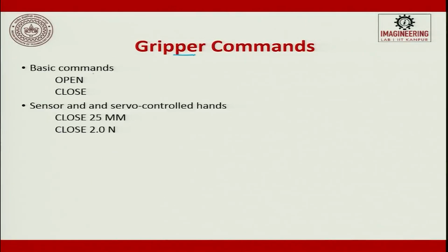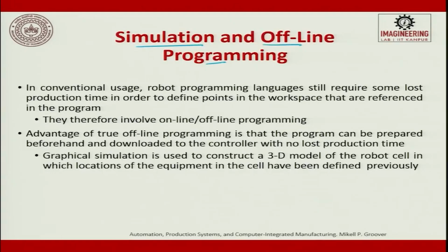The gripper commands can be basic open, close, or it can be close and wait or close with a load. So, it will be 25 millimeter, close at 2 newtons. Now, the simulation and offline programming.